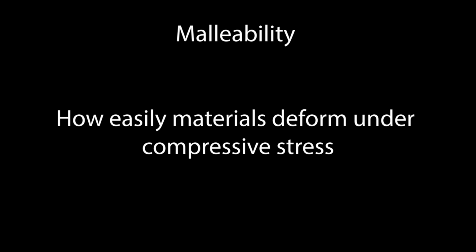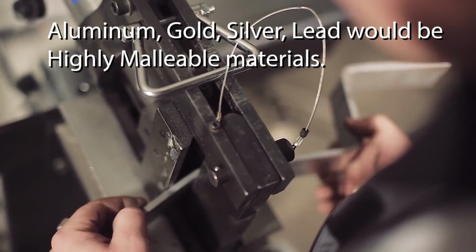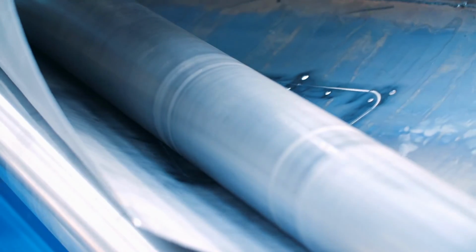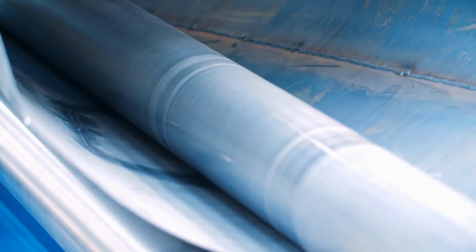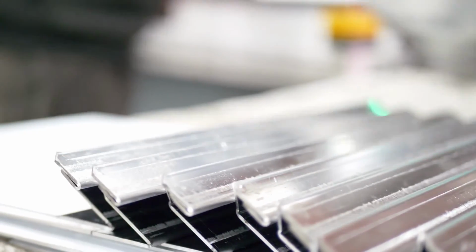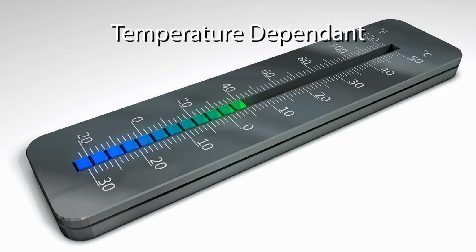Malleability. Malleability is the property of solid materials which indicates how easily a material gets deformed under compressive stress. Malleability is often characterized as the ability of a material to be formed in the form of a thin sheet by hammering or rolling. This mechanical property is an aspect of plasticity of material. Malleability of material is temperature dependent as well. With rise in temperature, the malleability of the material increases.